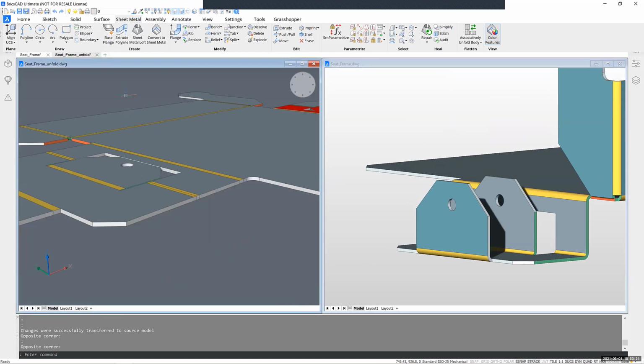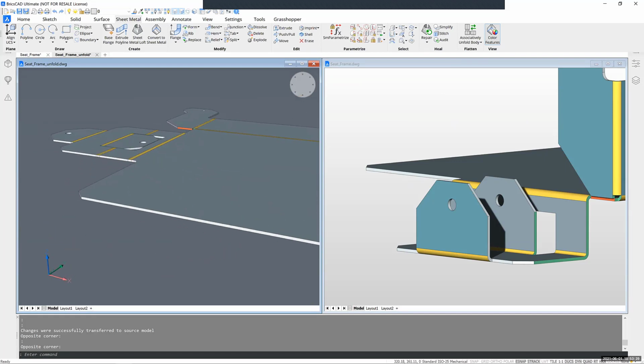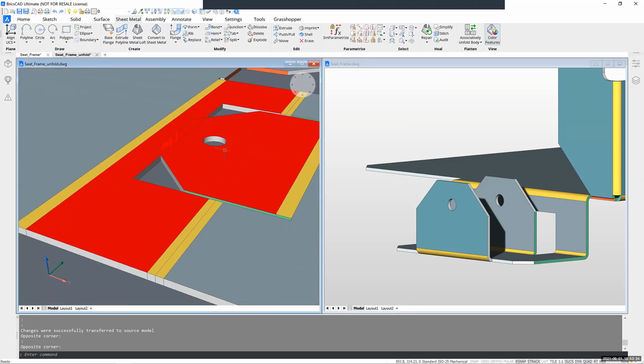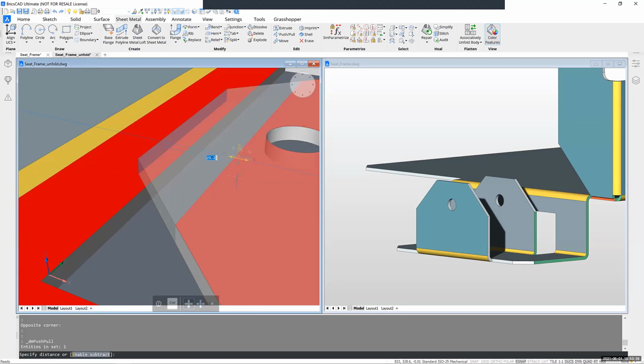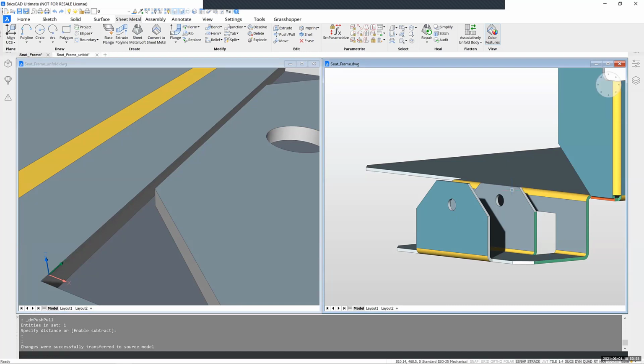So I will rotate my view so that I can access the other flange easily. Right, and then I can select this face again with tab, push-pull it, make sure that it's not subtracting, push-pull it back with 10. Oh, yes. And then it turns blue here. So it means that it's unfoldable. And then I click here and you should see this change, hopefully this time. Yes, and I saw it changing. So that's what you want.